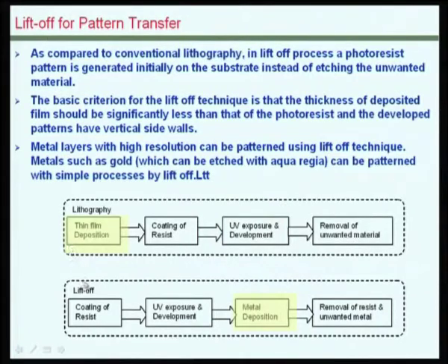Whereas in Liftoff, what is usually done is you first coat the resist and then transfer the pattern by UV exposure, and after that deposit the thin film.